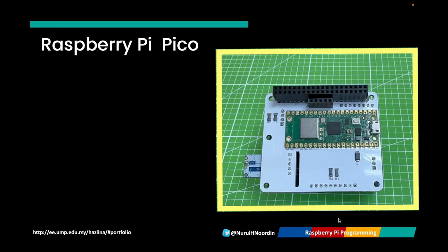One of the key advantages of the Raspberry Pi Pico is its low power consumption. It supports multiple power modes, including sleep and deep sleep modes for battery efficiency, and 3.3 volt logic levels, making it compatible with many low-power sensors. These features make the Pico ideal for portable devices, IoT applications, and real-time control systems. While Raspberry Pi Pico lacks built-in networking and high processing power, it is a cost-effective, energy-efficient solution for projects like robotics, automation, and sensor-based applications.